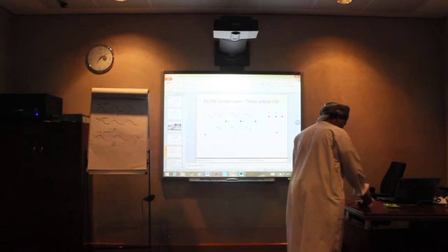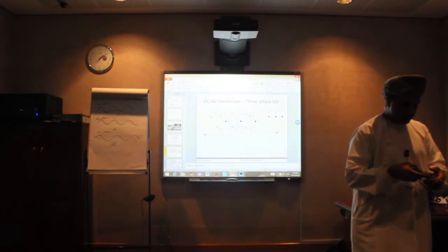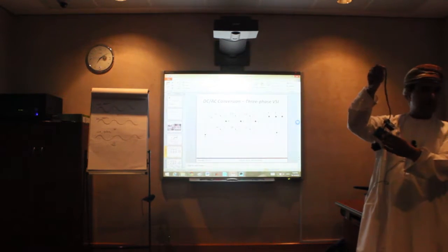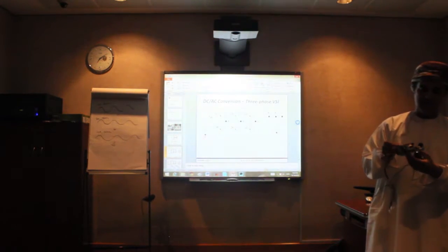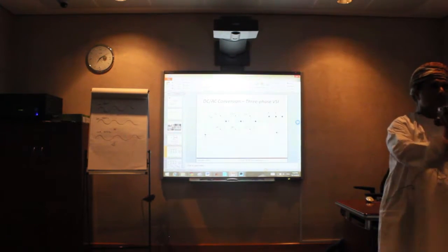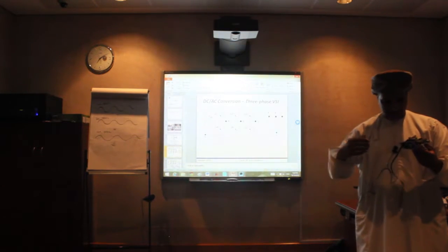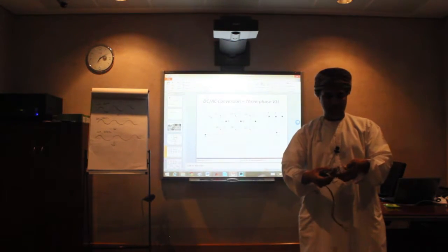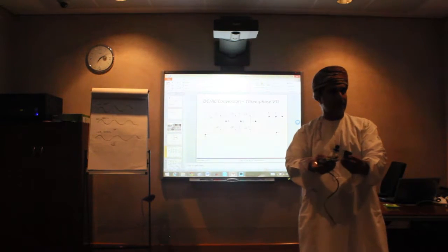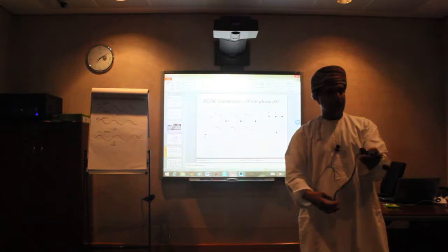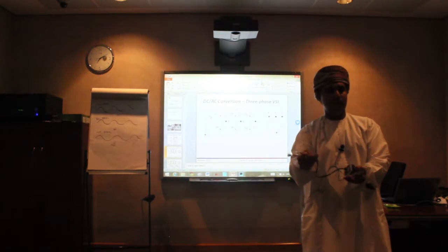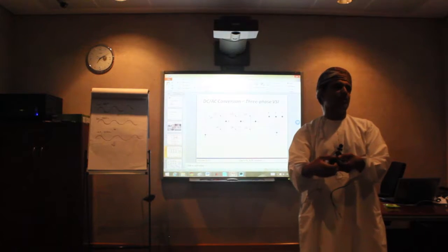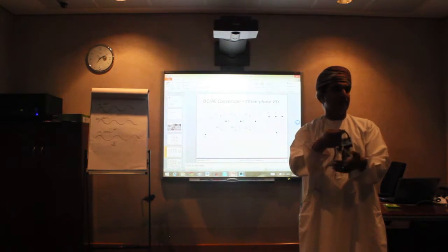In addition to that, if you look here, this one is a single phase DC to AC inverter. It's 200 watt rating, and it has two options. This is the input. You can get it for 12 volt input. And the output, this is AC output. You can get AC from here. So that means you can even take power from your car battery, and then you can get AC. You can run a TV with less than 200 watts. You can operate this circuit.